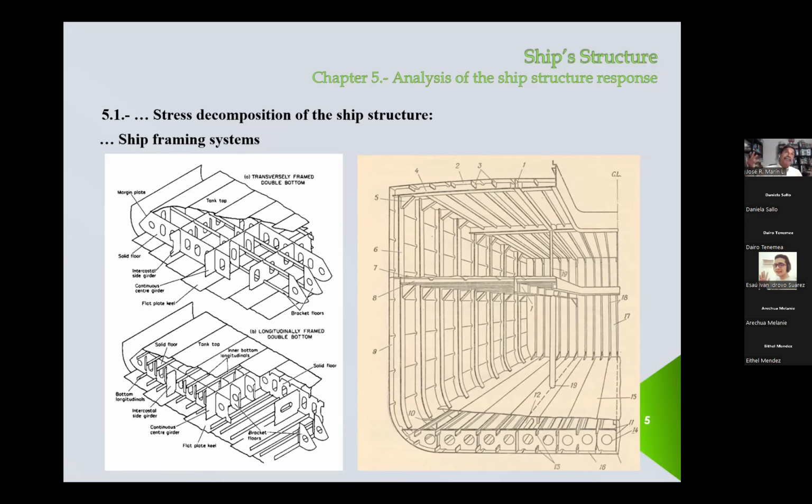It's just a technical visit. Try to learn from that. Again, similarly, what's the spacing between girders? A girder is a strong element. So you see that the strong element goes up to the bulkhead. Fine, but in the bulkhead, you have to prepare a very strong connection. Try to learn how it is connected to the vertical reinforcements of the bulkhead.